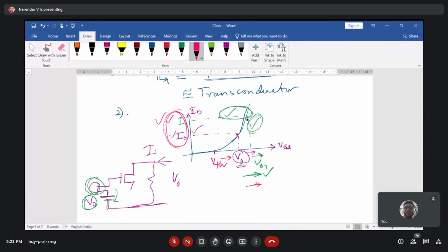Yes, when you are increasing the VGS value higher and higher, and here VGS refers to the biasing voltage, you are superimposing your analog signal on your DC biasing and applying it to your transistor so that it can amplify. As you increase the value of your biasing voltage, that is your VGS value, more current flows in your transistor as it is further away from your VTH value. With a higher value of VGS, correspondingly you have higher current in your transistor, and this current causes